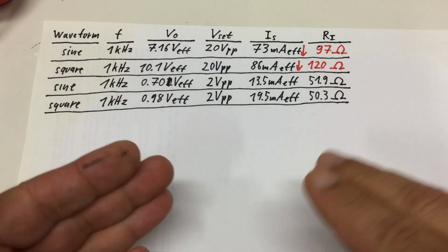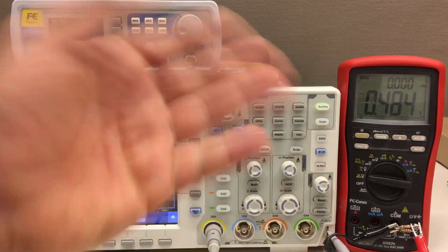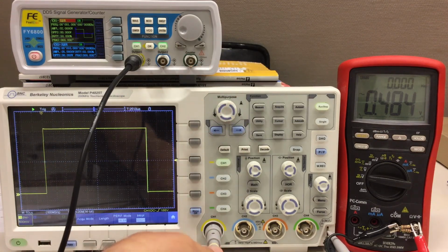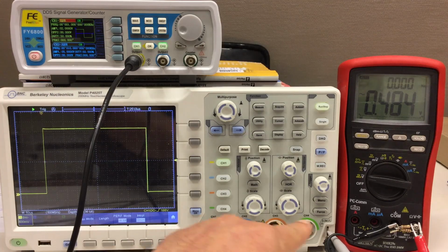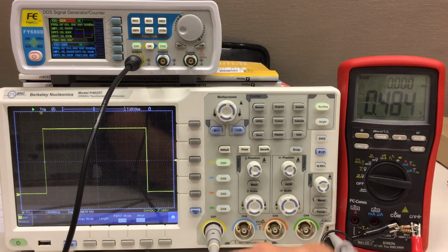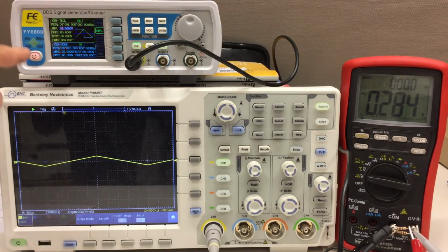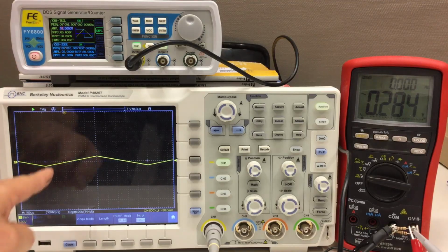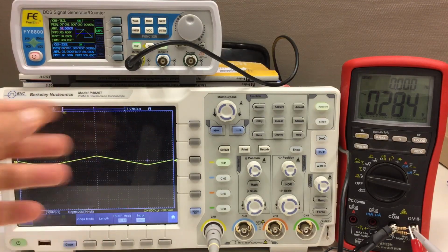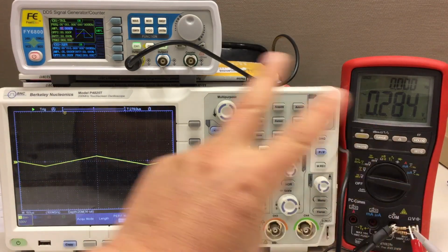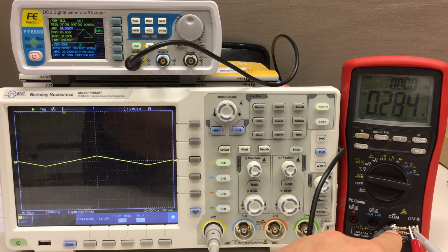I guess it's time now to get the oscilloscope out. And just for those of you who are rightfully concerned about probe compensation, I just compensated the probe with the 3.3 volt square wave output of the scope. Yeah, it's connected here. So my function generator is still at 1 kilohertz and 2 volts peak to peak nominal output, but I changed to a triangle wave. As you can see, the reason will be clear in a moment. And it's driving a, well, nominal 50 ohms, so 49 ohm load.